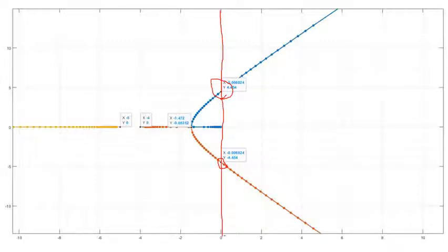Look at here guys, this is 0. So obviously this is the imaginary axis for you, and you can find the root locus which we have considered. One will start from -5, the other will start from -4. The -4 root locus will move towards the origin, and at the origin also a new root locus will start. So exactly the same plot we are getting here.